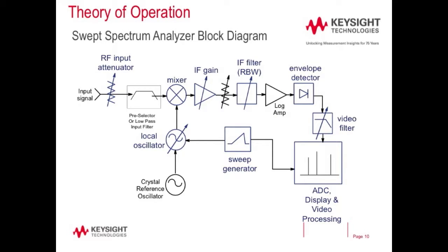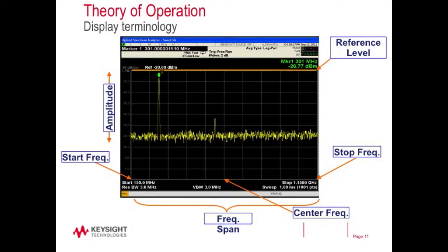So again, this is a typical screen for a spectrum or signal analyzer. So on the y-axis here we have the amplitude, so that tells you the magnitude of your signal. So here you can see we have a marker on there. So marker 1 corresponds to minus 27 dBm, and if you look at the scale, you can see that's between minus 20 and minus 30 dBm. And this reference level up here that we're referring to right here, that tells you what the signal level is if you had a signal touching the very top line. So you can see that's minus 20.